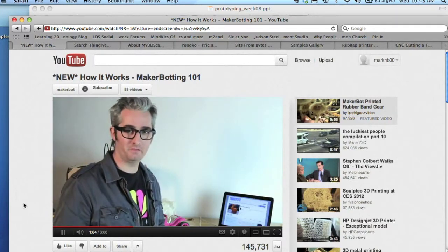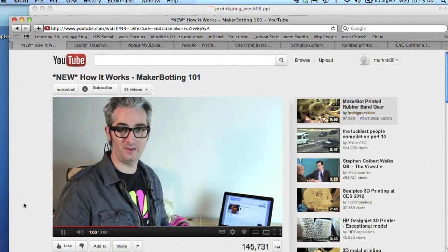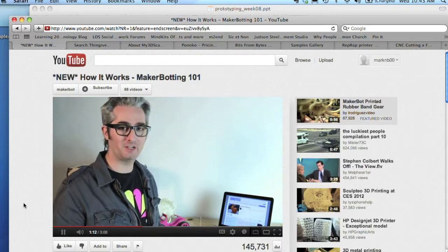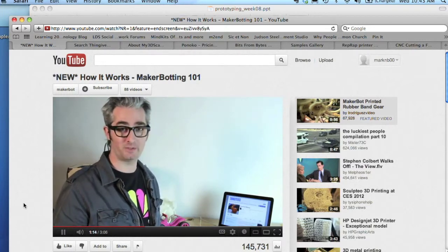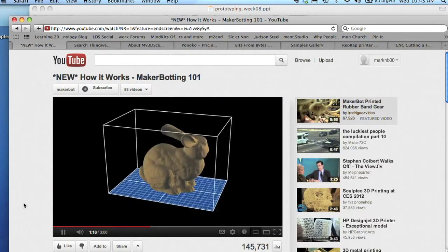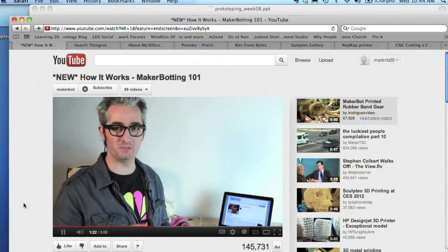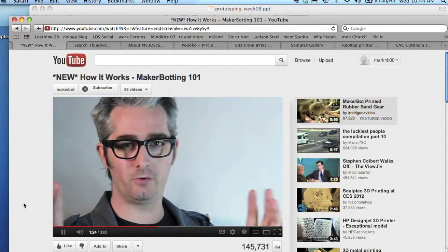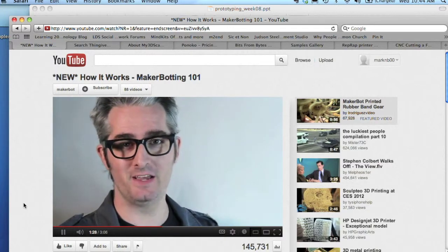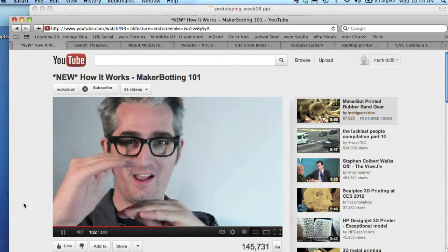I'll show you Thingiverse in a minute, but you just download. Find something you like on Thingiverse. Click on the file name and download the file to your computer. Now you've got the digital design for that object. Open up ReplicatorG and load your file into ReplicatorG. Here, you can move it around on the platform, you can scale it to make it bigger or smaller, and then you're ready to create some G-code. G-code is an old school format that tells the machine what to do. Then you press print, and the machine jumps into life and starts making your object one layer at a time.